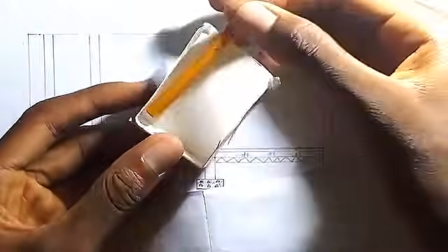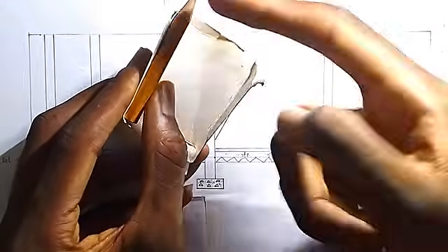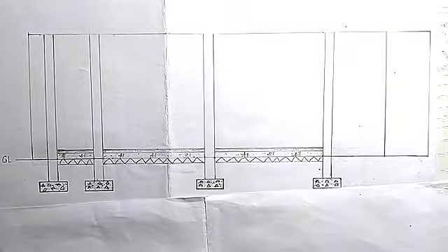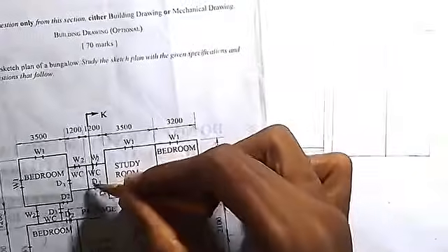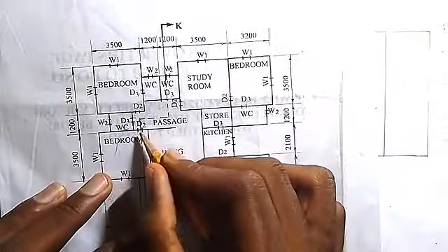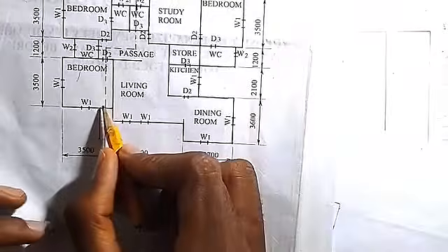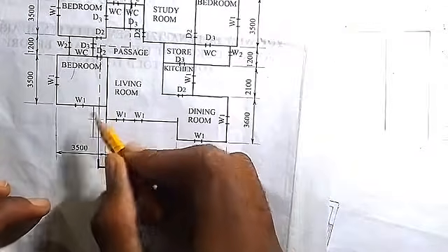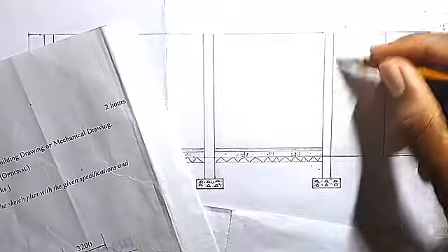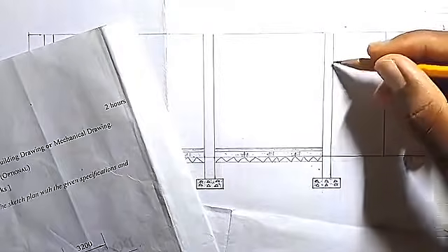So now let's say the wall is this pencil and this is the width of the wall. So what are we seeing? We are seeing from the edge, this side here, which it cuts through, which is what we are going to draw. So that's what we are going to draw for the wall. For this part, it cuts to the door, which is here. So we put the sign, the mark for the door. In the other wall here, it cuts through the door too. Also put the mark for the door. Then for this other wall, it has only wall here, and it cuts to the wall. So we also put the sign for a wall.